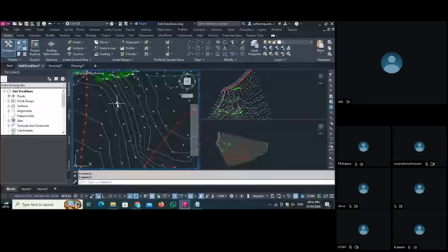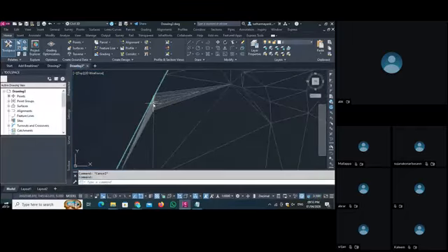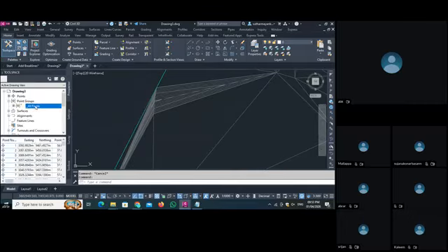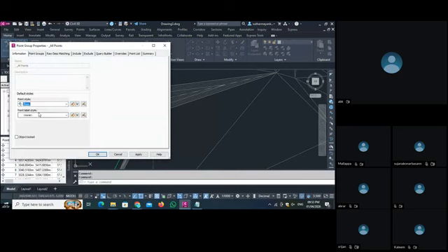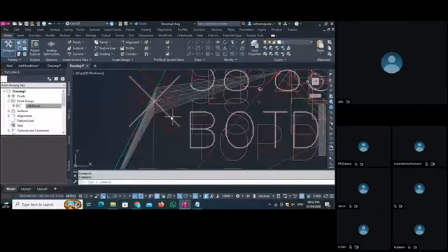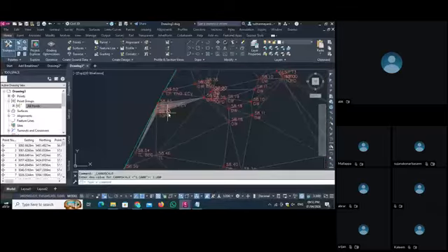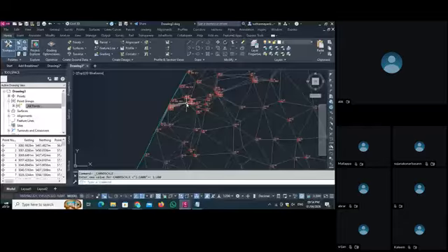As we have all the points here, we go in our file, and we have a problem that we cannot find the things here. So where we have the problem, for that we go here in a point group, go in properties, and take the point style as basic, and elevation and description. Apply and okay. See, I set my point as 200. Now there is one point which has a zero elevation here.